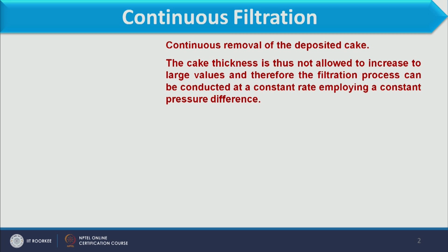For example, this is the filter media, cake formation appears over here, and as the thickness of this cake increases, this cake offers resistance in the path of the filtrate to cross it, and therefore after some time the volume of filtrate which has to pass is reduced after continuous operation.